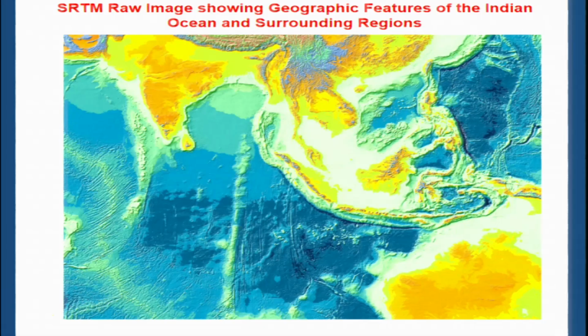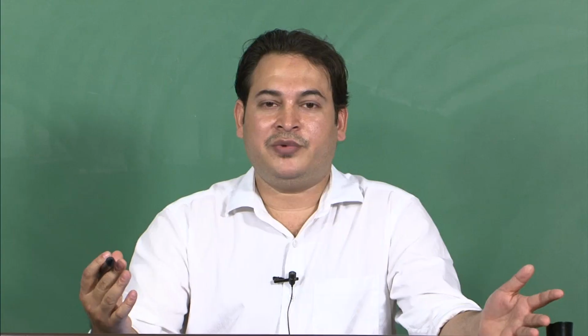So digitizing, the word known as digitizing. Suppose we are able to see the boundary of this landmass, then to highlight this boundary is called digitization. Digitizing the map means highlighting the boundaries which are obvious or which are doubtful but can be confirmed from other sources like Google Earth, some other satellite images.